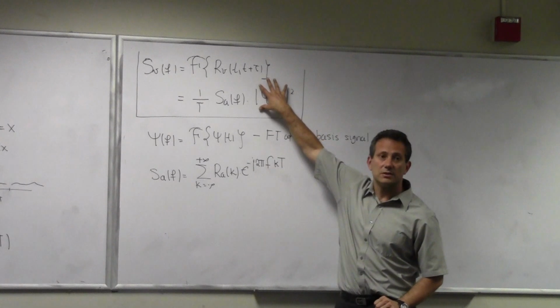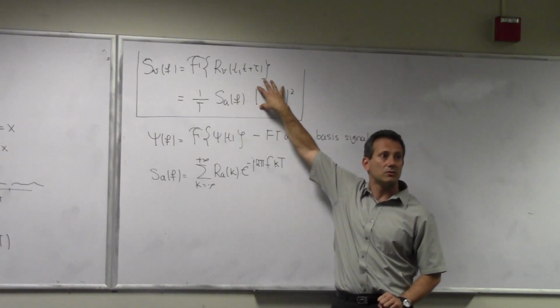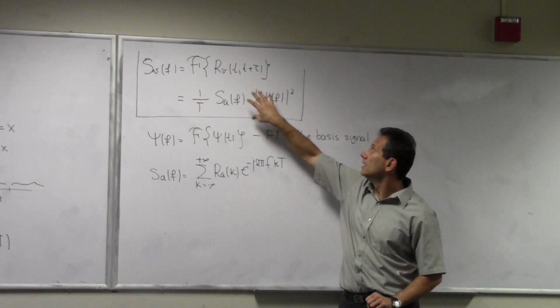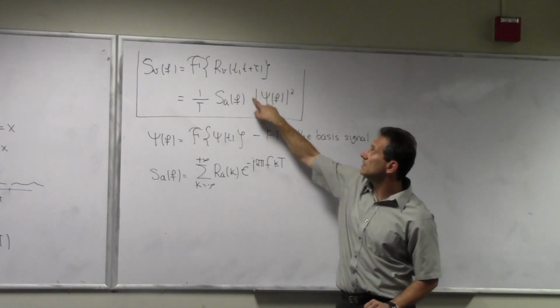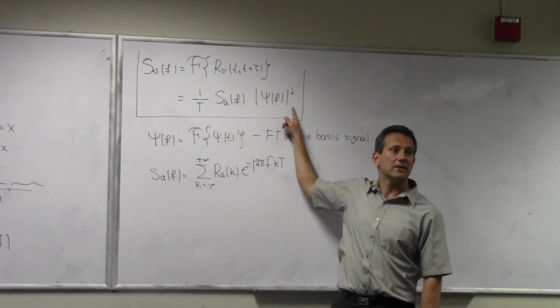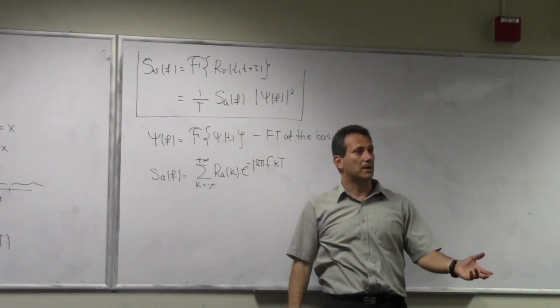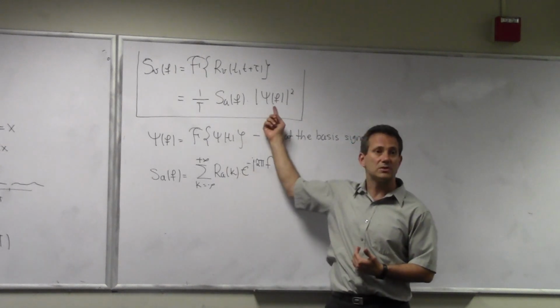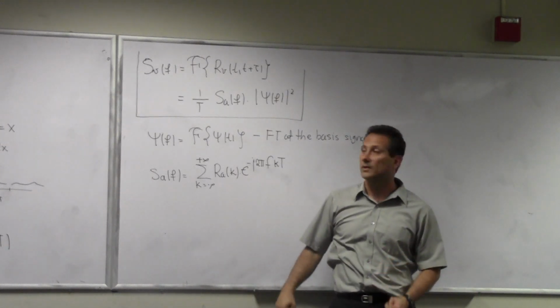One effect is the shape of your pulse, the shape of psi(t). This is what you start with, and this one is easy to determine. This is something that is absolutely in our control; this is what we select for the signal. I could have selected psi(t) to look like a square pulse. Then this becomes a sinc, so my signal looks like a sinc in the frequency domain.